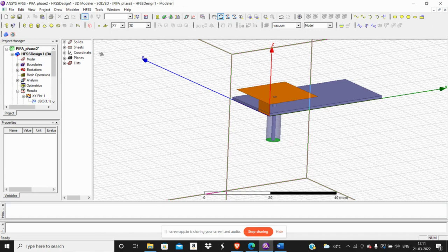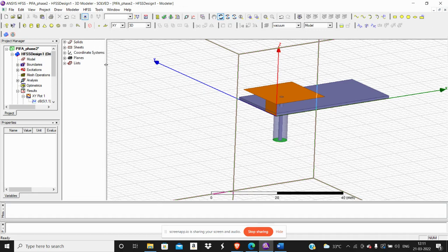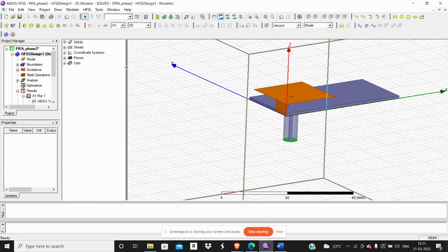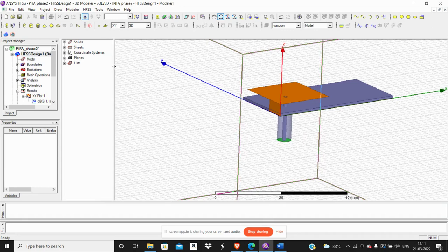Whenever you are designing an antenna, you mainly need three things, right? We need the resonating frequency, or where you want it to resonate, and you need the substrate dielectric constant as well as the substrate's width, right? There are some steps of designing. First is the actual designing of the antenna, as in the physical design. You're designing the ground, the substrate, the patch, the shorting pin, the feed line, everything, and you have the radiation box. You design the physical design.